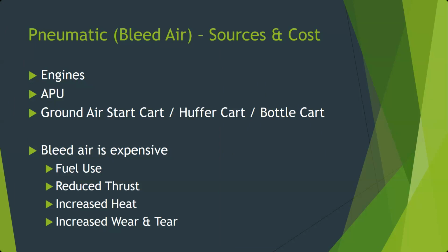In that case, they've been able to make it more efficient by putting bigger, more powerful generators on the engine. The generators operate electric compressors that provide bleed air for pressurization and environmental control. They don't use it for heating the leading edges, though. The leading edges are electrically heated. And I believe the thrust reversers are hydraulic, but I'm not 100% certain on that.